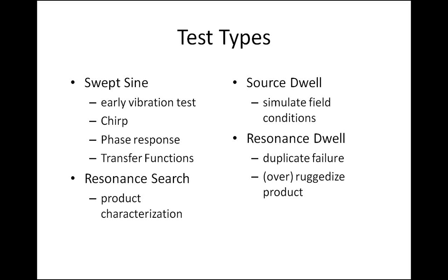When we look at sine testing, it's one of the first real closed loop tests that became available, and swept sine was intended to address the issues of mainly aircraft, turboprop aircraft early on. The other types of tests, random, shock, random on random, mixed mode, different tests, basically came on after that to simulate different conditions in the field.